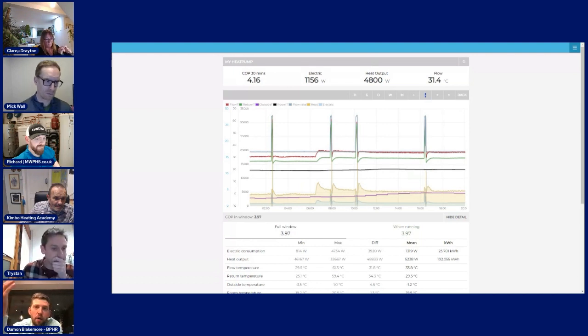Because if you just go, I want a 16 kilowatt, that's where Valent is a little confusing, because people have been used to different sizing with different manufacturers, and you get into outputs from similar units, like a 12 kilowatt Valent to a 12 kilowatt HJ. The output on them is not 12 kilowatt at what you're wanting. They both differ. So there's loads that you need to know and look at to get this right. There's so many steps where you can trip yourself up with it.